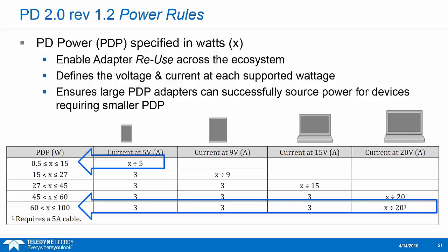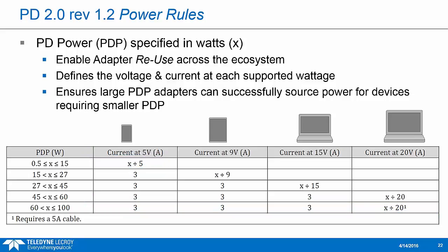This is why they added the 9-volt rail, and really it's all around delivering a better user experience. If you just grab any power supply off the shelf, you don't want to burn up your device. Initially, the focus was on AC power adapters, wall warts. But as it's written now, all USB Type-C devices are required to specify a PDP. So for ports that can act as a provider, we'll now check that they report all the required PDOs from this table.